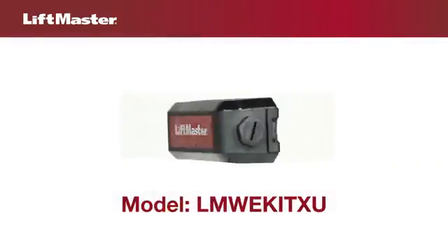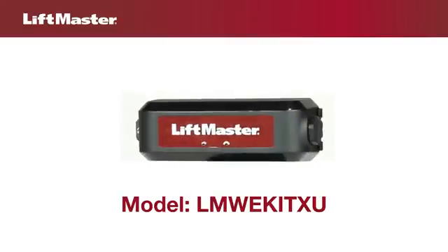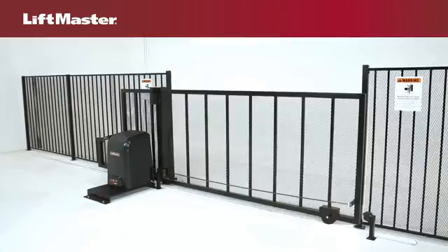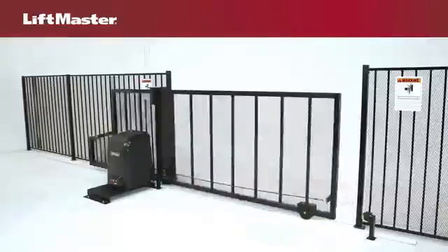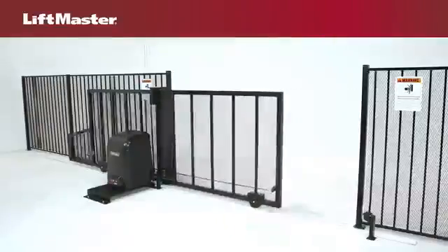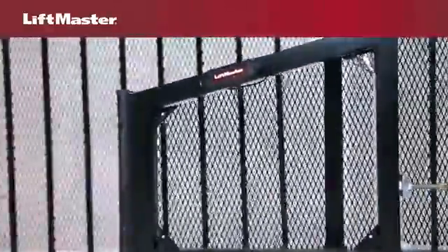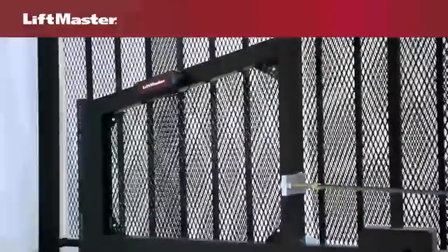Let's choose a LiftMaster electrically activated edge sensor for the open entrapment zone. Edge sensors are contact sensors. They are activated when the edge on the gate comes in contact with an obstruction while the gate is moving. The gate will reverse and then stop. The obstruction will have to be cleared before the gate will travel in the open direction.